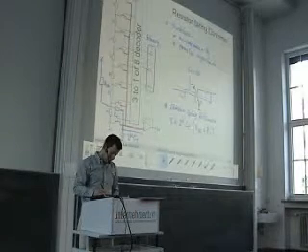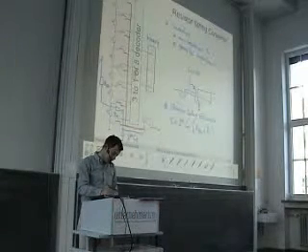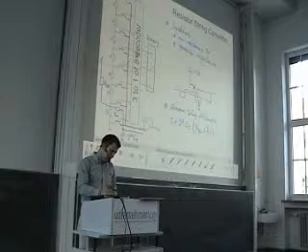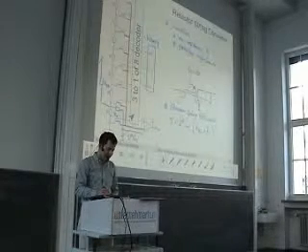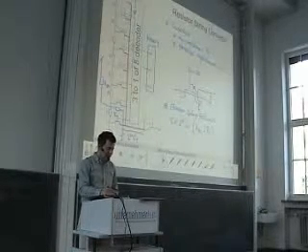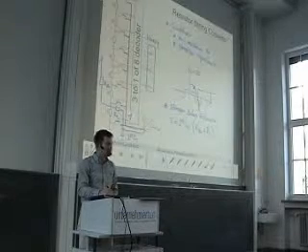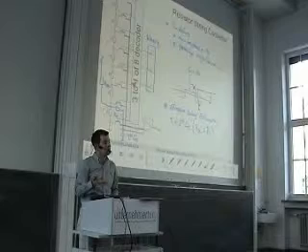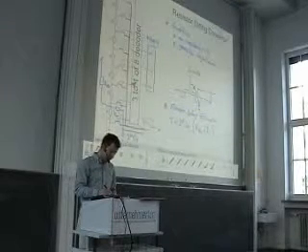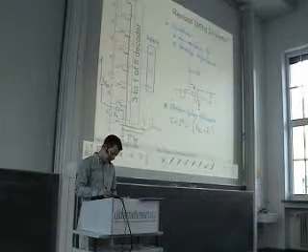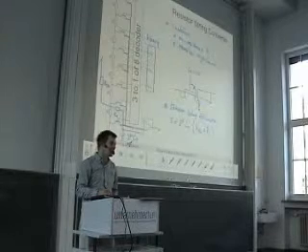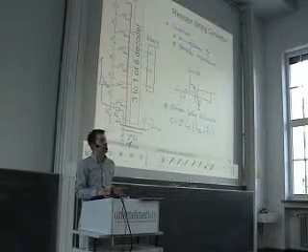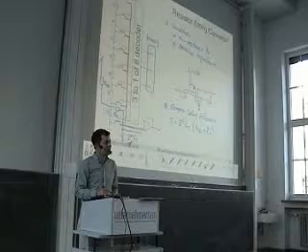And also we have to say that this decoder logic is nowadays really negligible. Having a couple of gates to do this decoding is, in terms of area and power, really negligible, so we can do this. However, if we go to a higher number of bits, then you can see that this parasitic cap here scales with 2 to the power of n, so scales much faster than in the other case.